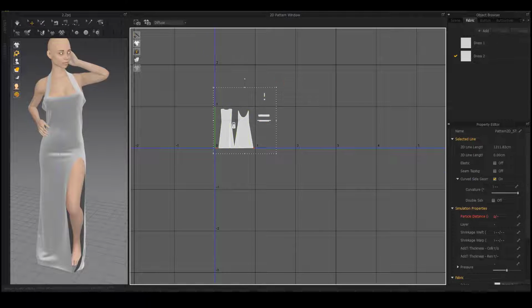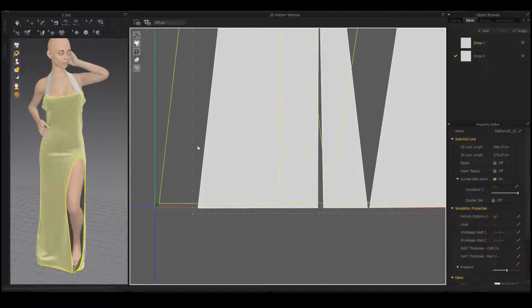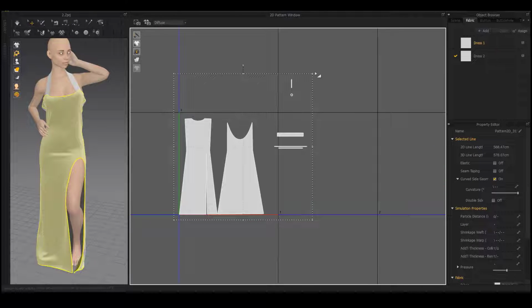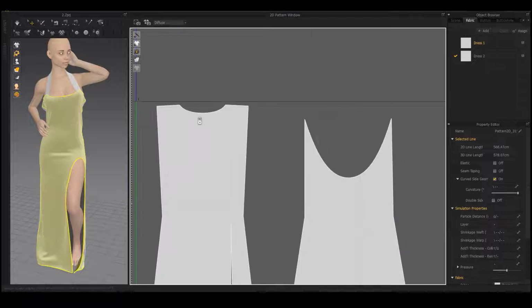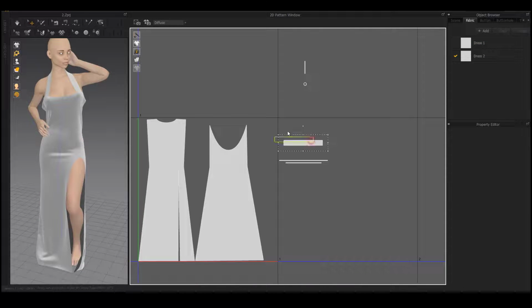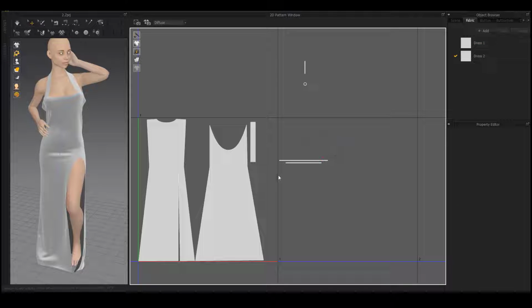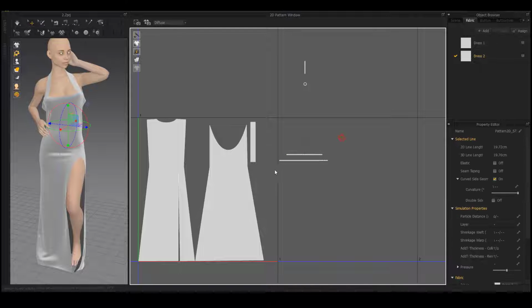If symmetrical paste is used when making clothes, it is necessary that when making UV, the bonded clusters should be completely mirrored. Otherwise, when making normal material, the fabric in that series of parts is made in the opposite direction. You can set the unwrap type based on UDIM, and set the whole clusters on 2 or more UV screens. In this case, each of the clusters will be placed in a larger size, and the texture will be placed on it with higher quality.